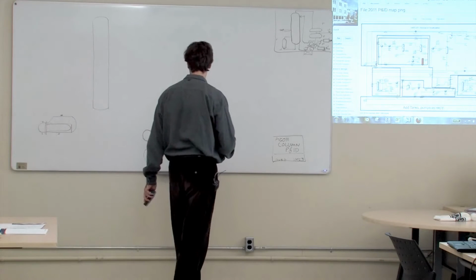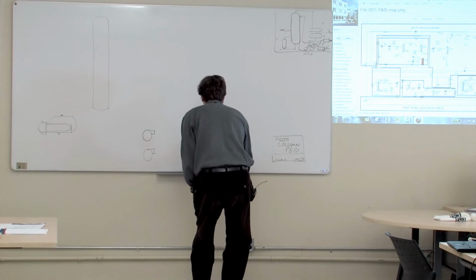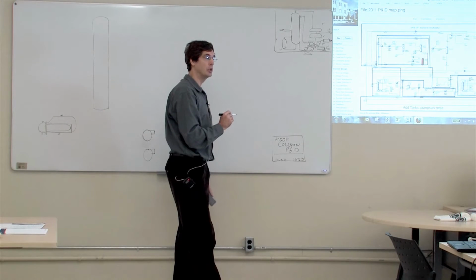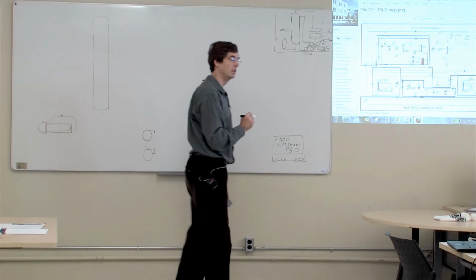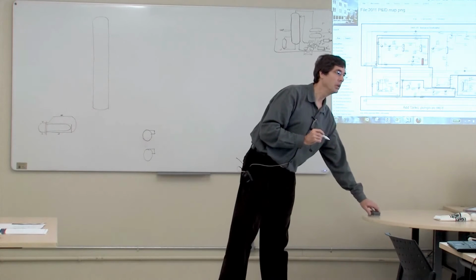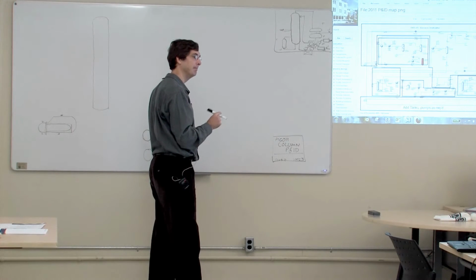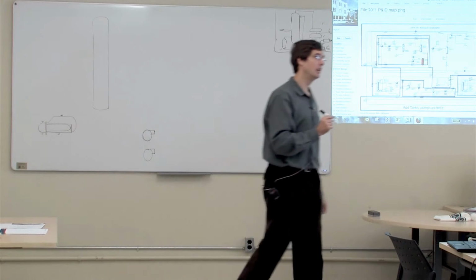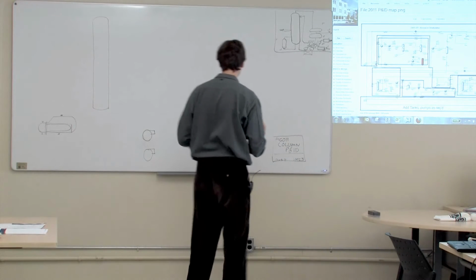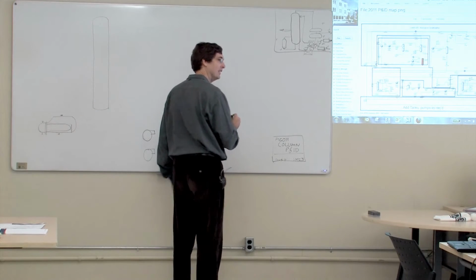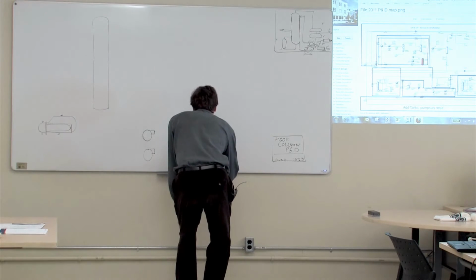Let's put the bottoms cooler in right now. What kind of bottoms cooler did you guys build? Shell and tube, yeah. You know what TEMA class it was? An AE what? How about an AEU? Okay.